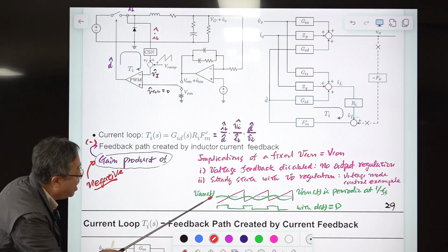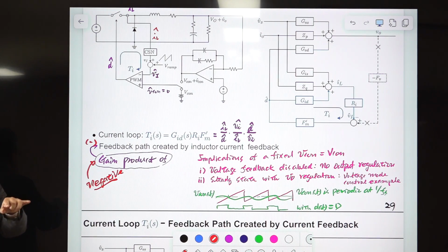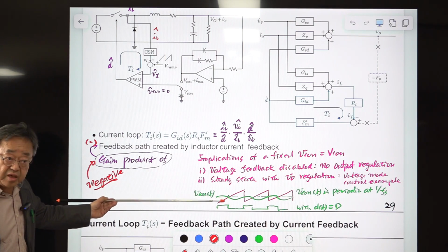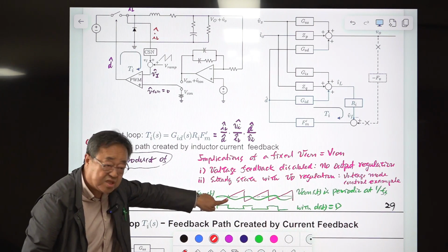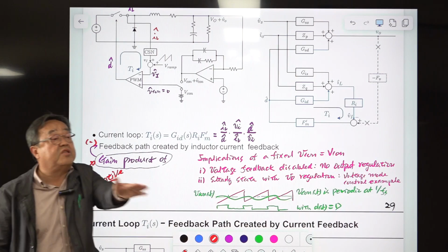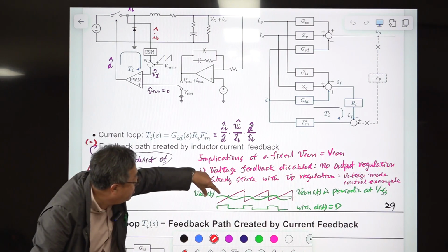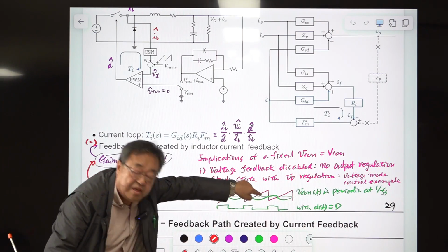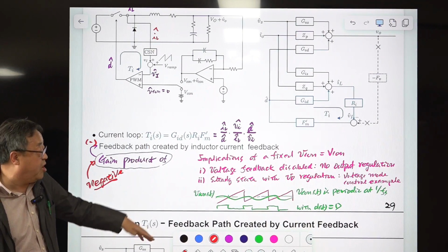But it contains this sinusoidal oscillation at the switching frequency. That occurs always. If you simulate your closed converter and expand out the waveforms here, the control waveform looks like this. They are varying sinusoidal waveforms, but this point is fixed. They have a sinusoidal disturbance, but the disturbance is adjusted to have the same point at every switching cycle. Then that maintains the duty ratio constant.